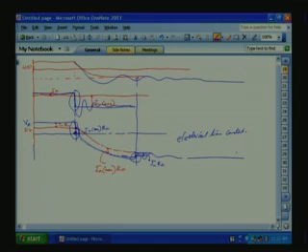Let us take, if you use a phase control converter for high power applications, how we will control the 4 quadrant operation with the DC motor. We will very quickly go through that, and then how you make the firing sequence, the firing control for a phase control converter. Sine triangle PWM is easy to generate, and we will see how phase control is generated. Then we will come to the closed loop controller design of the DC.